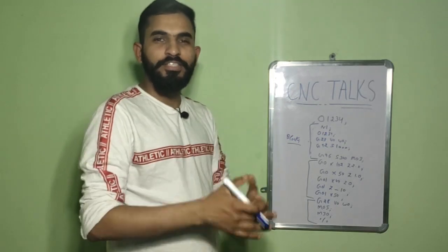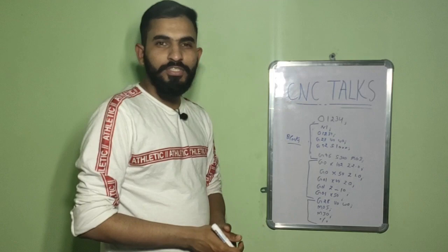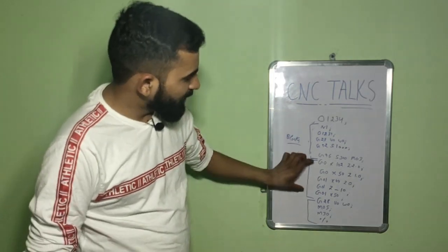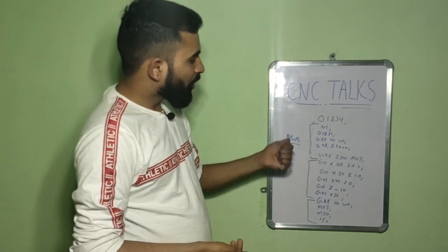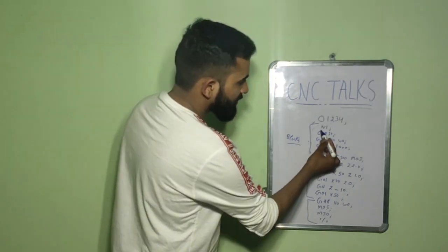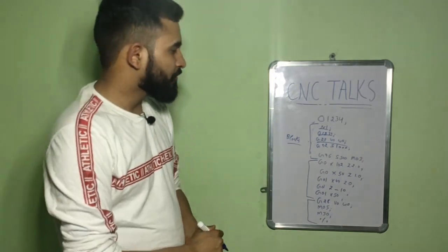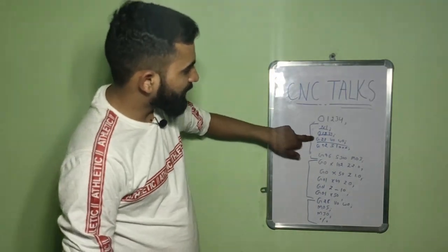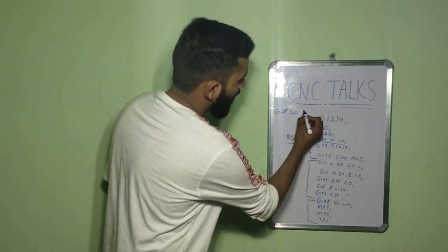First of all, let's understand what is a program. So a program is basically a set of blocks. As you can see, there are certain number of blocks which are joined together to create a program. Each block consists of a number of lines, and each line contains a number of units. So for example, in this line there is G28, U0 and W0.